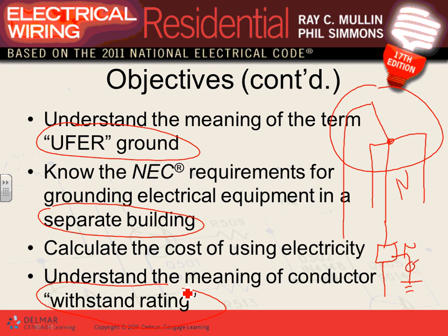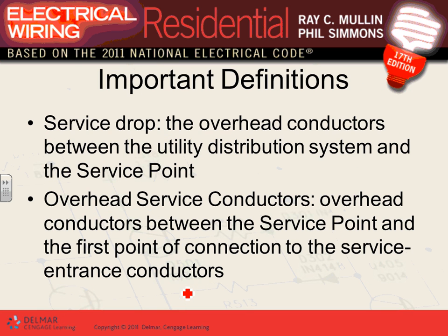So withstand is how much power are you pushing me with, and for how long? So that's the energy, right? When it comes to a conductor withstanding a current, it depends on how much the current is and for how long. Remember, the how long is as important as how much. So that's your withstand capability.